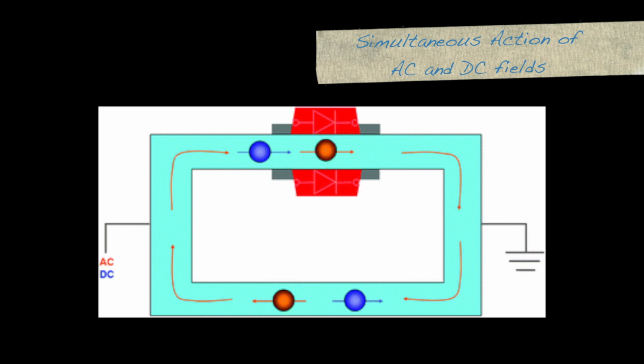So here shows the schematic of the concept for efficient separations during the electrophoretic transport of a fluid and analytes in a loop-shaped channel under the simultaneous action of AC and DC fields. This is called diode pumps, which will allow decoupling of the electro-osmotic fluid flow from the electrophoretic solute motion. So if the loop channel has diodes placed on one side, then the AC field will be rectified to drive the fluid in circular motion in the channel.